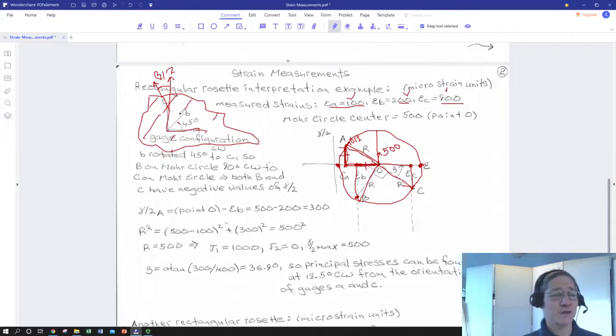You can place that gauge oriented any way you want. So if you already suspect that one direction might be a principal direction, there's no reason to not put one of the gauge directions on it. You notice that EC isn't too far from being the principal direction. So this angle beta isn't very big, actually.